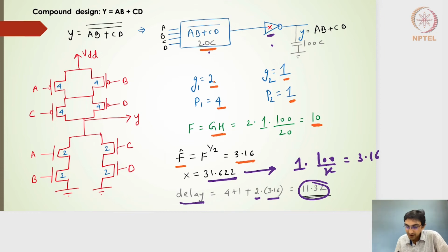All right, and then if I have an input capacitance of 20C or a gate size of 20 here for the AB plus CD the whole bar, we know that for the individual input 6 parts have to be created, and then 4 parts of the 20 should go to the PMOS side, and then 2 parts of the 6 parts should go to the NMOS side.